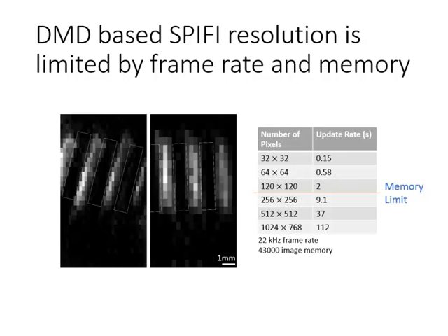The unfortunate aspect of this type of image formation is that while the DMD has a relatively high frame rate of 20 kilohertz, because we need to wait a long enough time to be able to separate out each of those different frequency components, we need a very large number of images, and so the DMD can only hold 40,000 images, and thus can only run for about 2 seconds without being stopped and restarted. It really puts a hard limit on the number of pixels you have.